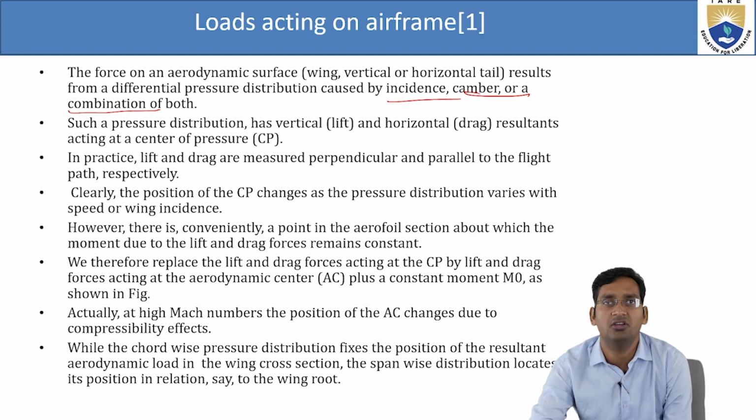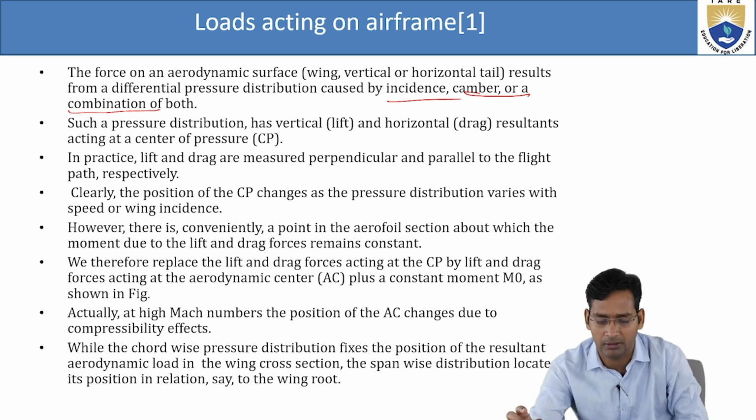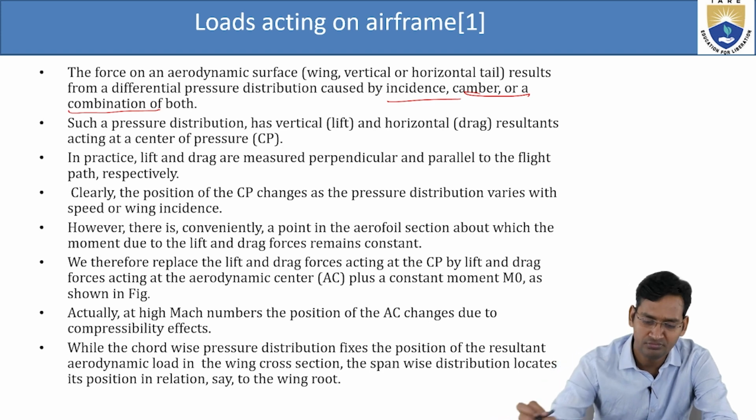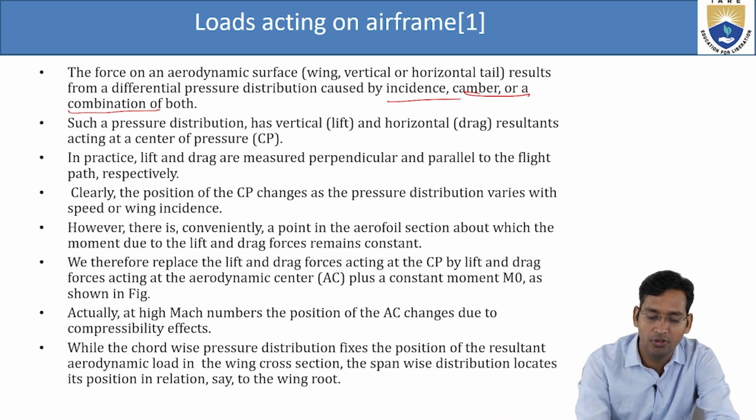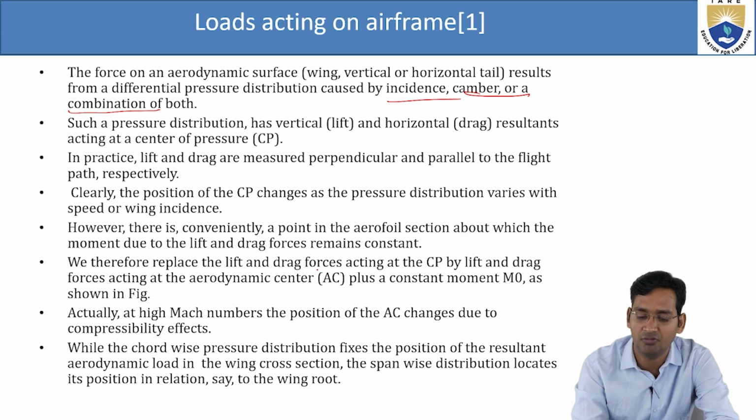However, there is conveniently a point in the airfoil section about which the moment due to the lift and drag forces remains constant. We therefore replace the lift and drag forces acting at the CP by lift and drag forces acting at the aerodynamic center, AC, plus a constant moment M0 as shown in the figure.